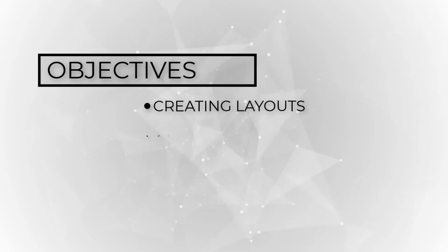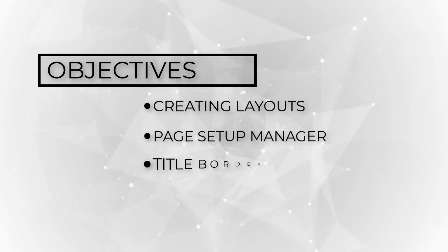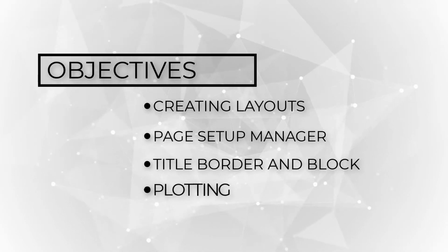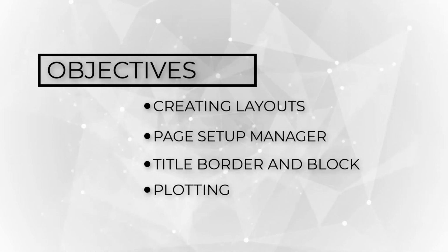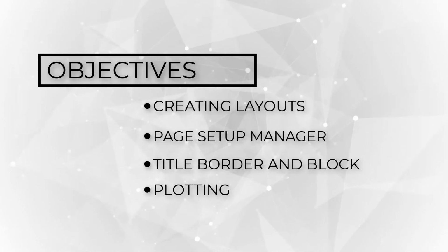This video will basically cover creating layouts and the page setup manager. We're going to create our title border and block, and we're going to set up how to print our templates by plotting.